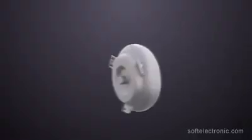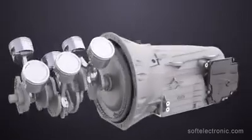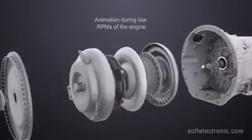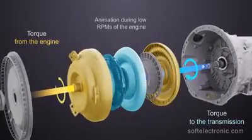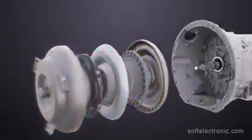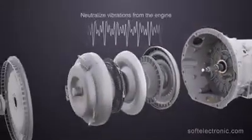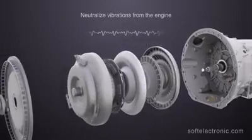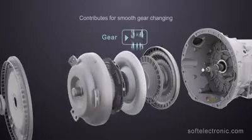The torque converter is a fluid coupling between the engine and the transmission. It has several main functions. It increases the torque from the engine to the transmission when the vehicle is moving. When driving off, the torque is increased at most. It operates the oil pump in the gearbox. It helps neutralize fluctuations and vibrations from the engine to the transmission. It contributes to smooth gear changing.